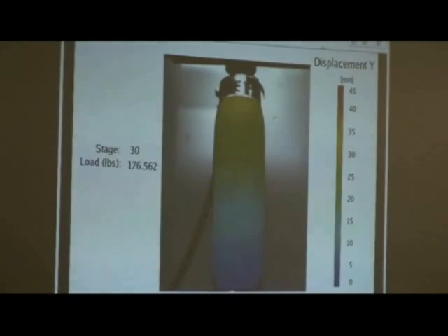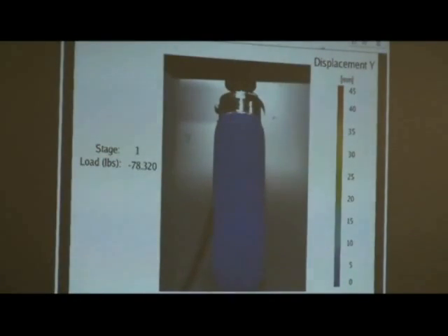Likewise, we could have displayed strain, and I'll show you that in a minute. But it gives you an idea of how this technique is typically used. It's typically used in mechanical testing of dog bone specimens for either compression tests or tensile tests. If we have a strain gauge on this, you get information at maybe one point. But what we're getting is information over the entire structure.